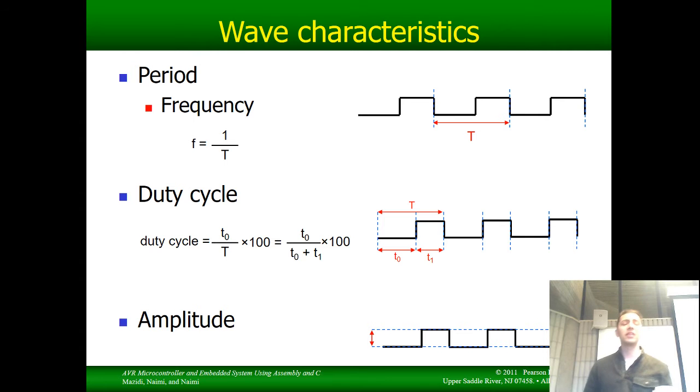A couple of things that you do need to know. Any of you ELEs will get used to this pretty quickly. Things like the frequency of a waveform. We're generating square waves with our digital logic. The period and frequency of a wave are inversely related. So if you know the time in seconds from rising edge to rising edge or falling edge to falling edge, you know its frequency by doing 1 over the period.